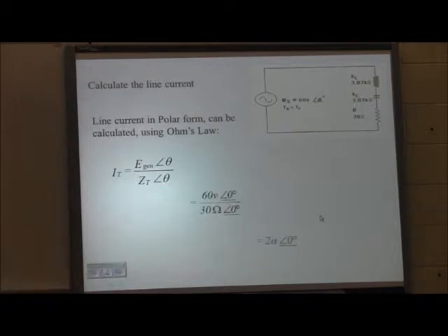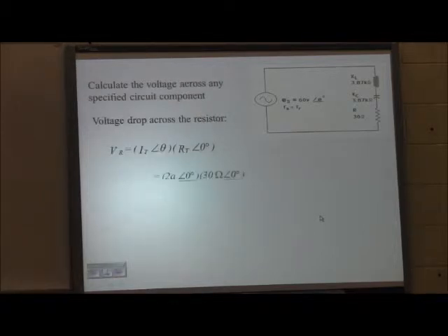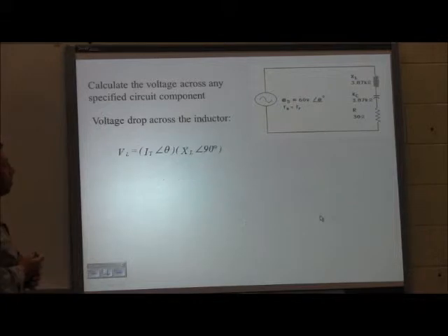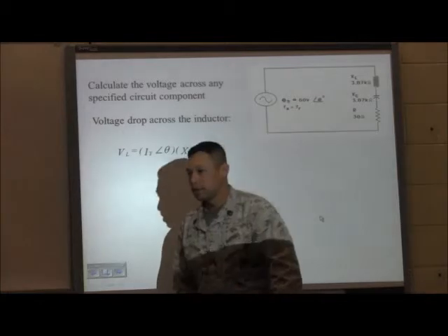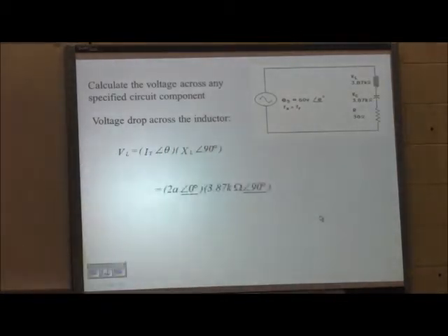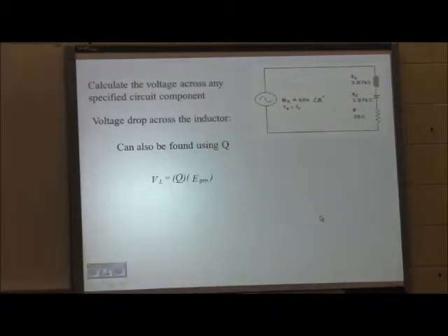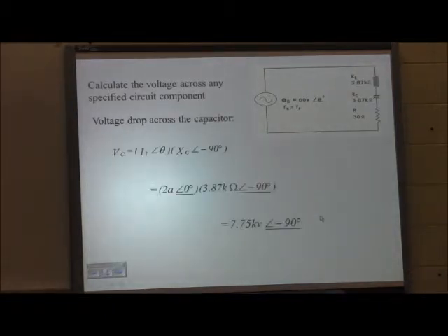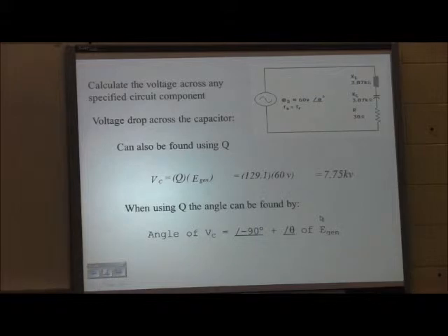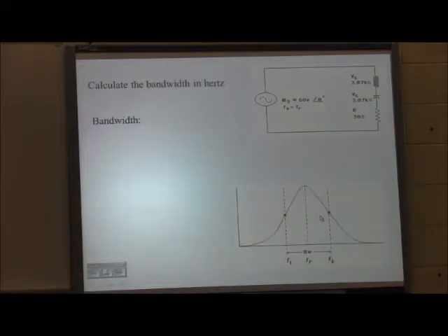So this is all at the frequency of resonance. All the voltage drop is at the resistor. What is the total voltage across the inductor and capacitor at resonance? The total voltage drop across the inductor and the capacitor at resonance is 0. Yes, it is 0. So at F1 in series, the circuit is acting what?